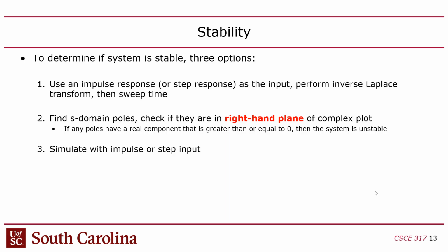So if you give an LTI system an impulse or a step, you're exposing it to an infinite range of frequencies, right? And if any of those frequencies cause it to go unbounded, then the system will be unbounded. So the step response is not the step, but the impulse response is a common way to test for boundedness, okay? So that's one way to do it.